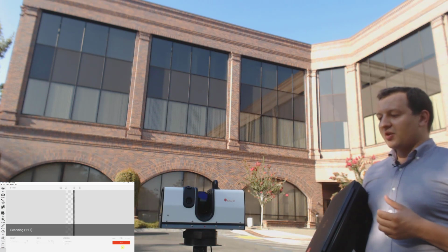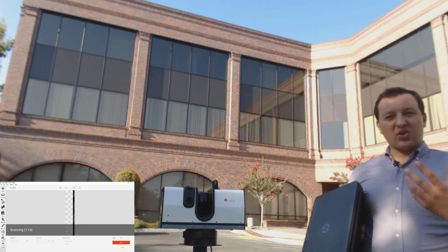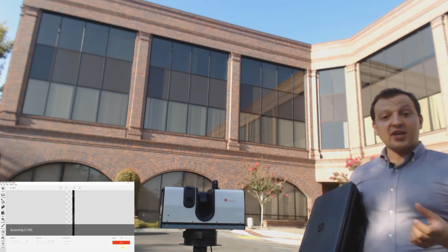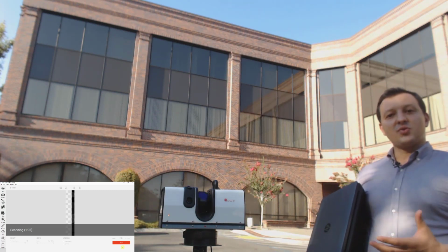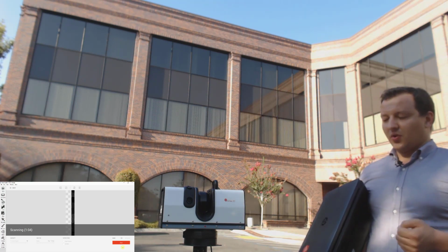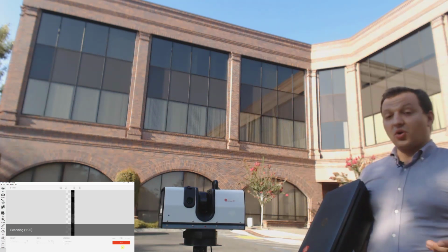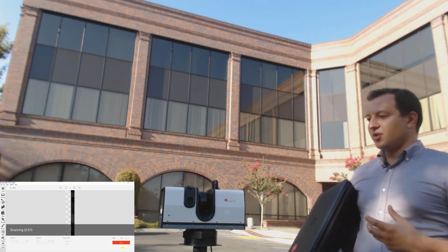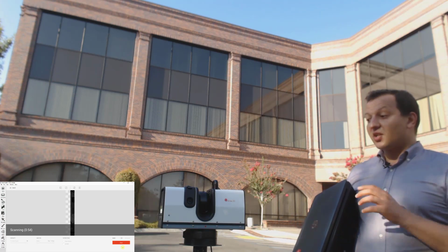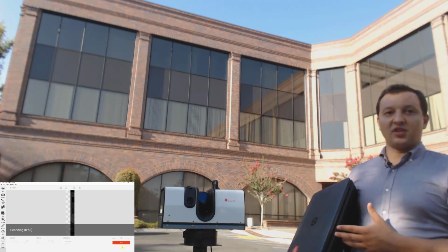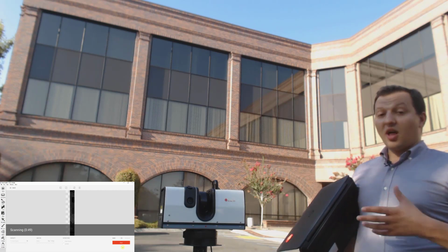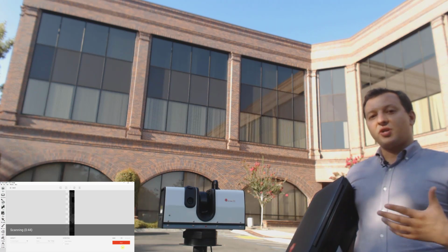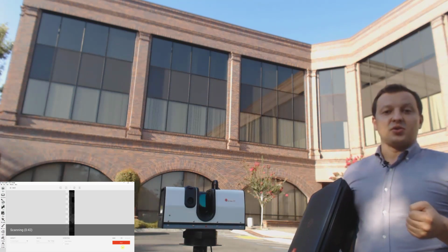But like I mentioned, this is one of those scanners that, due to how clean the data set is, due to not just the noise levels, but also the accuracy of the device, this data is actually usable in a reverse engineering context. So you could use this data to complement handheld scan data, which is a lot denser and a lot more feature-rich than LiDAR data normally is. And this was deliberate. This was the intention of the device, to give you a LiDAR scanner that can scan huge volumes, but with the capabilities of a small handheld unit.